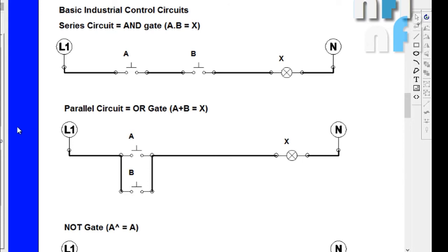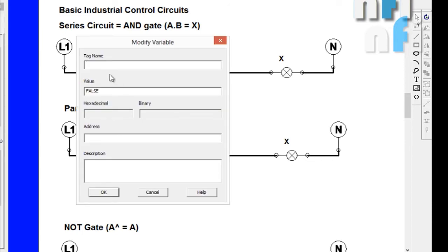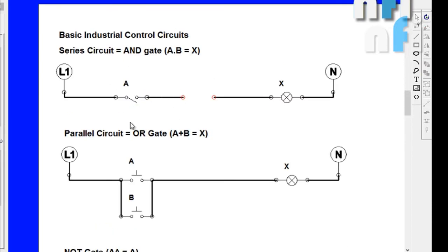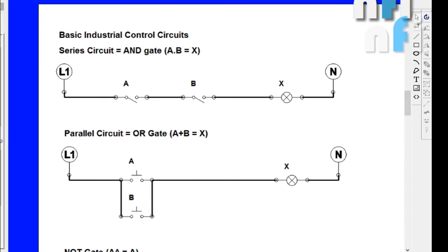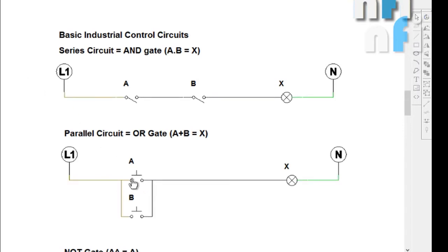So the next thing we are going to do is the latching, but before latching I just want to share that we also have a toggle switch. These toggle switches do not have a spring. They maintain the position once they are actuated. They are generally used in household actuation. Bell switches are typically push buttons, but when you turn off a light in your room, that is a toggle switch. When you press this button, it will remain here, and you press this one, this will turn on. There is no spring here, otherwise it's again normally open, similar to this one but without a spring. They retain this position.